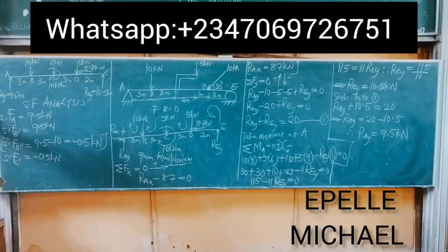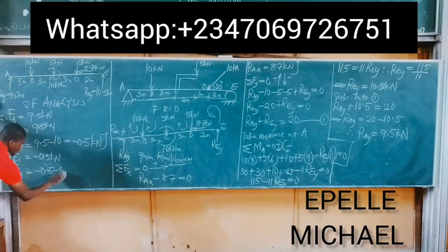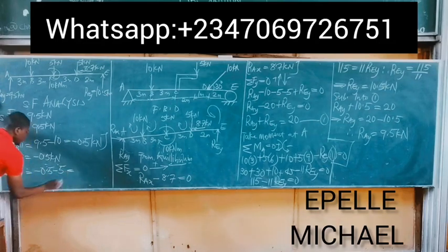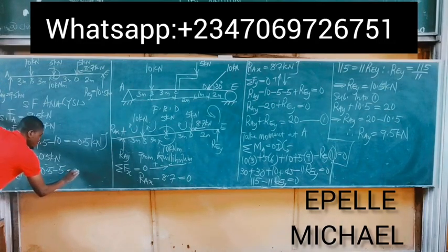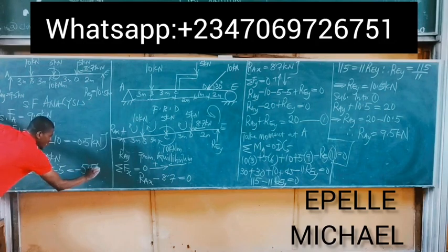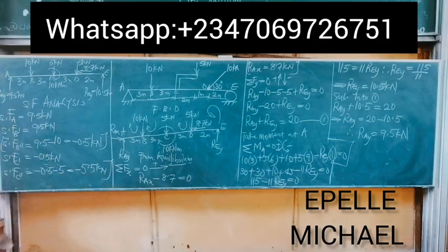So, shear force C prime prime, which means finally at point C, this same minus 0.5 kilonewtons force now encounters a downward force of 5 kilonewtons. So downward, we simply add minus 5, and that gives us minus 0.5 minus 5, which is simply minus 5.5 kilonewtons. So you keep this aside.